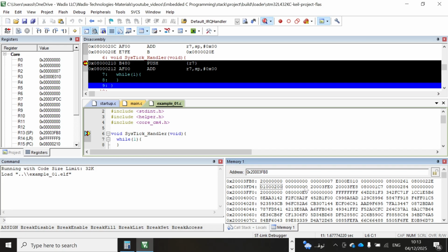So instead of pushing the XPSR register as the first element, the hardware has decided first of all to push those extra 4 zeros, then start pushing the different CPU registers. With this extra 4 bytes, we'll be able to have an 8 bytes aligned stack pointer.